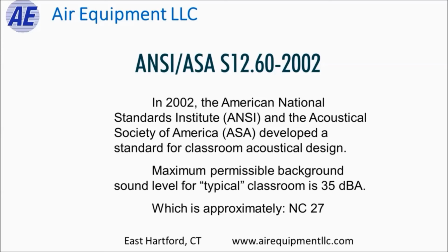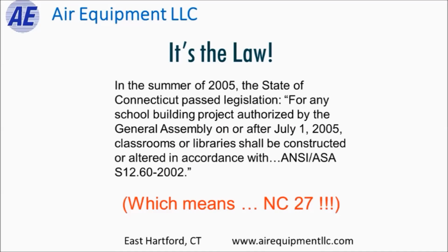Now this is quite a change, because prior ASHRAE guidelines called for an NC level of about 35 in classrooms. So this new standard is much more stringent, much quieter. ASHRAE has always called for an NC level of 25 for a performing arts center. So the classroom design standard now is just slightly louder than a performing arts center.